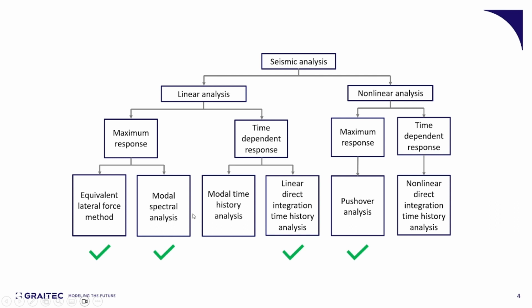The difference between the first two and the third one is that the first two provide the maximum response, so they give the maximum value of the displacement, or the response of the structure to be more general, whereas the linear direct integration time history analysis provides a time dependent function of the parameter examined each time.